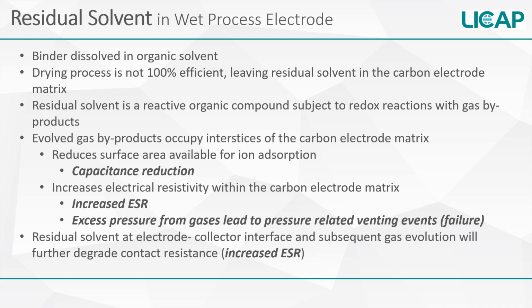As we've seen previously, gases adsorbed into the porous carbon electrode matrix lead to both reduced capacitance and increased ESR, and can also contribute to additional internal pressure and a possible venting event, depending on other operating factors, temperature, current, voltage. Additionally, residual solvent and subsequent gas evolution at the electrode current collector interface can cause further degradation to ESR by increasing interfacial contact resistance. Licap's process is completely dry, so there are no residual solvent effects.